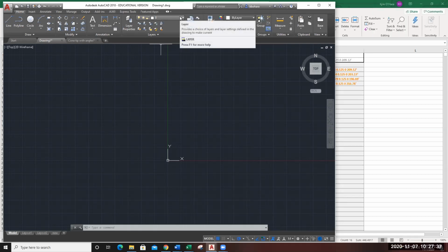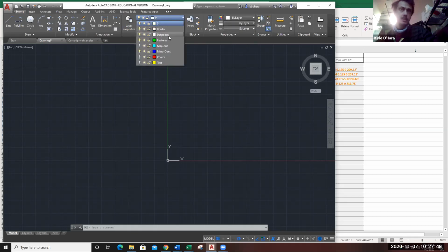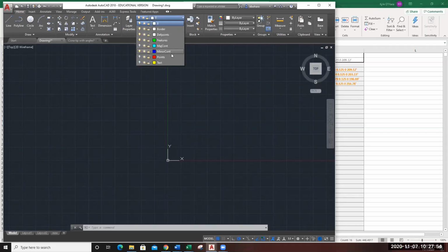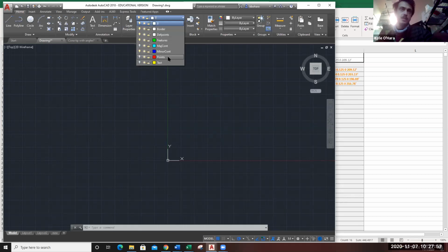Points and lines and some of the bushes and walls around it. Yeah, so features: environmental features, construction features, and you mentioned the contour lines. Yes, major and minor contour lines. Then also, in addition to that, we'd like to have points, and we might want to have some text associated with those points. So in AutoCAD, we want to make sure those are all separate. You might want to have different line weights associated with different features.